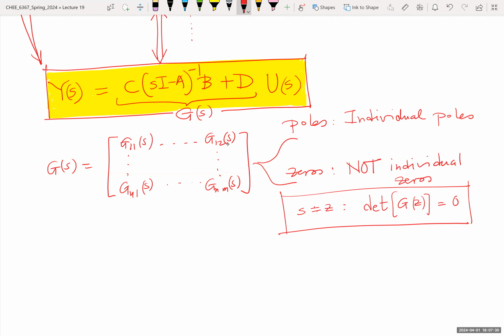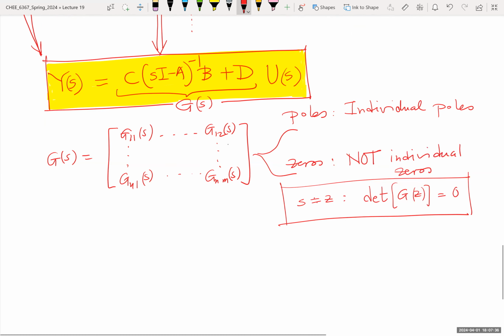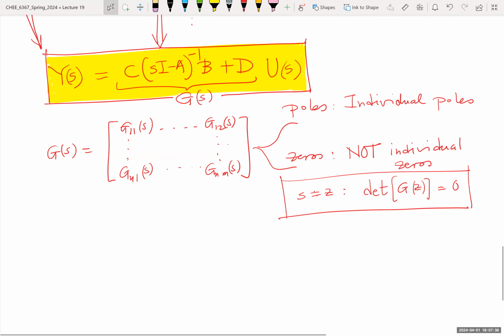And the explanation is in theorem 2 of the notes on page 6 that connects time and Laplace domains, and we'll see this idea a number of times. So a basic theorem, which is fundamental and very simple, is that the poles of G of s are the eigenvalues of the matrix A.